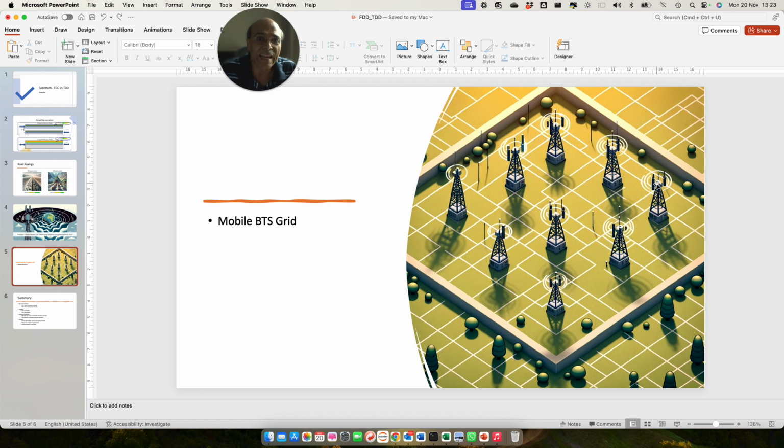So you have to take that factor into consideration so as to prevent that blockage. The receiver will get choked if signal is still in the air, transmitting in this direction and entering the receiver here, because when it opens up the receiver, that receiver will start receiving the signal which is already in the air. After 20 milliseconds, as soon as you stop and start receiving, you cannot stop the signals which are already in the air because they are transmitting.